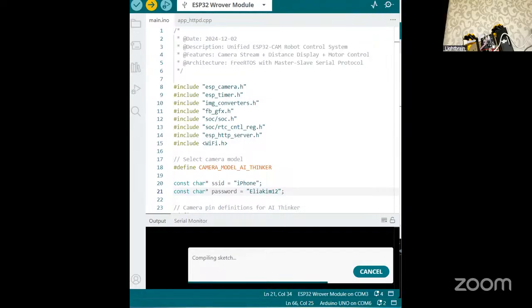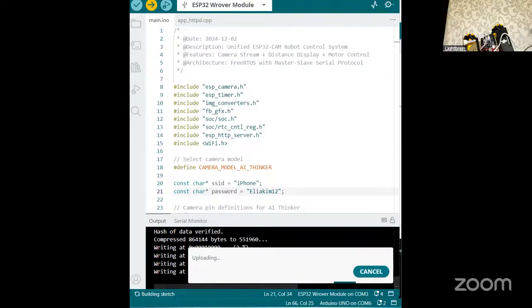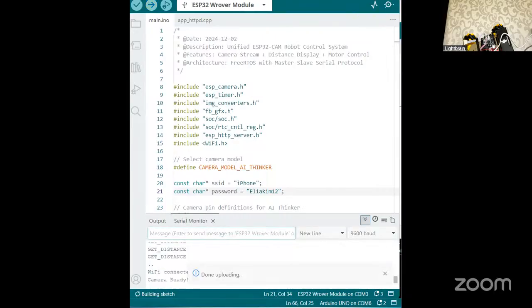So like I was saying, what is the big picture of all these projects? First, the Arduino will just be there to drive the motor and to measure the distance. The ESP32 does the Wi-Fi plus the web server and the camera, and controls the car from a distance. Okay. The serial language that will be talking there is just the language that the machines use to talk to each other, the boards used to talk to each other. Okay. The buttons of the web page are just there to command the Arduino. That is as simple as it can be. Okay.